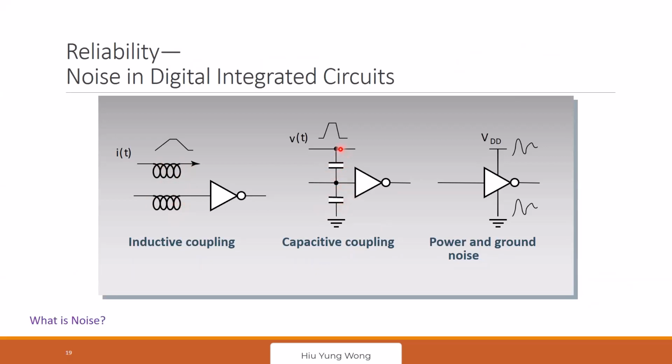So if your frequency is high, you will have more capacitive coupling. Okay? And also other noise coming from the ground and the power. This is something we need to redraw the picture in our brain. We always have to think about VDD is not next to you.